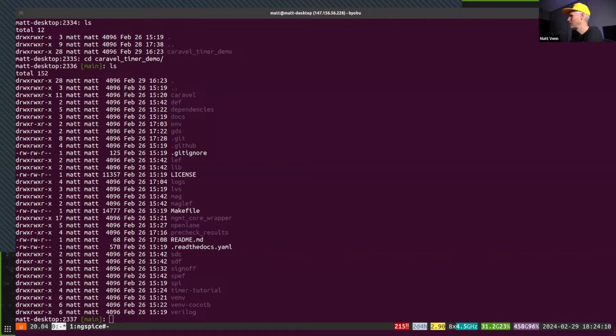Then we've got a couple of questions. Do I have to declare both input and output even though I'm only using the pin as an output, for example? We'll cover that in a bit. And is it possible to merge a custom PDK into the OpenLane? I'm guessing that means can you use a different PDK with OpenLane? It is possible. It's quite a lot of work to do. The easiest thing is to use Sky 130 or GF 180. They both work well. But you also need to think about, are you intending to manufacture? Because if so, then the only option at the moment is Sky 130.